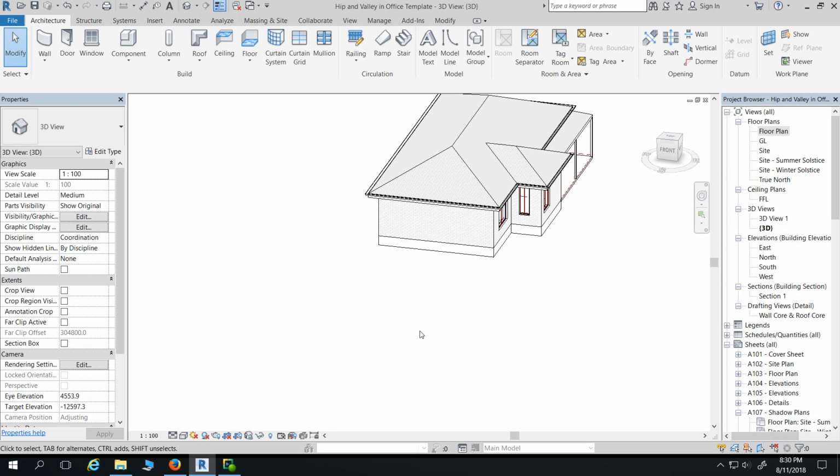So you hover over the edge, and hit tab now. So you just undo that. So you hit tab. See how I just hit it once, just press tab, don't hold it down. See how it's selected all of the roof now? You can click with the mouse. So just cancel that one. If you zoom in a bit, that's your fascia there.